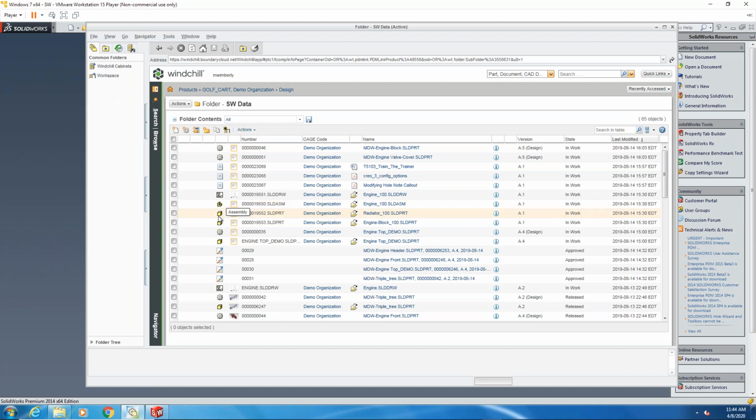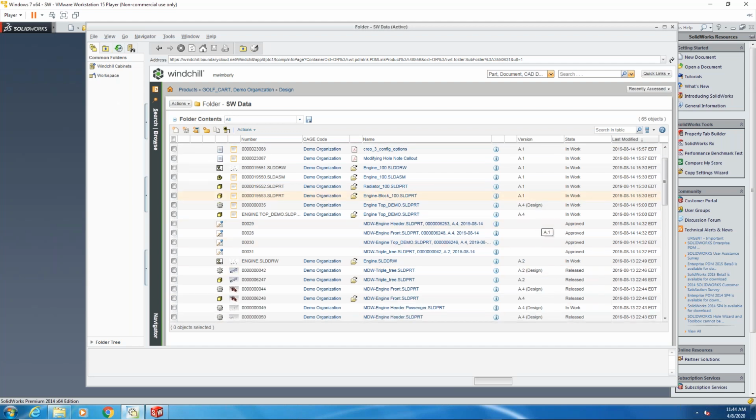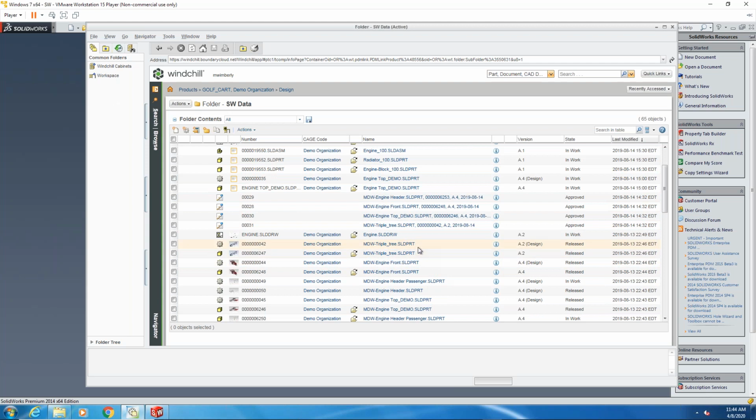You can see the SolidWorks icons for your parts and your assemblies and your drawings. Everything's there. I also have promotion requests that I've created inside of Windchill. So I can still go through and use the life cycles, just like I normally could, to make sure that each thing goes through its appropriate span. So from the initial release, which this one is in work, all the way till it's finalized at the release state. And just like using the actual Creo files as well, I can also have our WT part files directly associated with them as well.